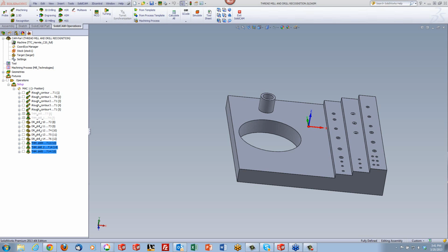This is an actual milling operation, okay, but using the center hole, using the geometry of a hole. However, as far as canned operations itself goes, that will be put and can be done inside your regular drilling operation, adding an option of thread mill, and that's with your post processor itself. You can ask your dealer, whoever your reseller or your SolidCAM support unit, to actually help you out with that if you don't have that yet.